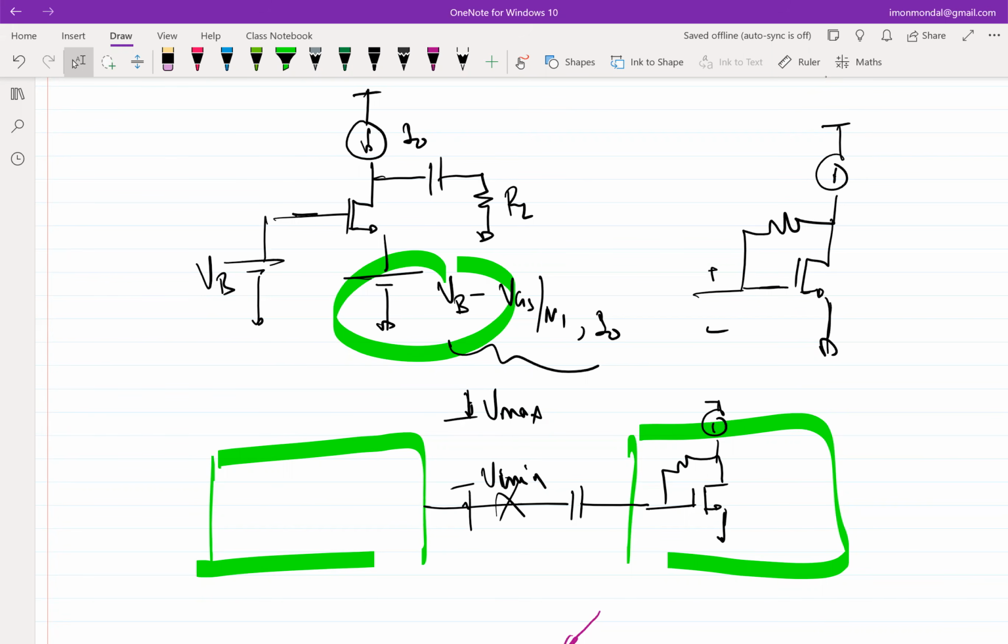That's what high resistance means. But when you are designing something in negative feedback, you are exactly trying to prevent that. So when you are putting your circuit in negative feedback, there should not be any high impedance node. If you have put your circuit in negative feedback in the design phase and you still find there is a high impedance node, which means something is wrong. Your design is not right.